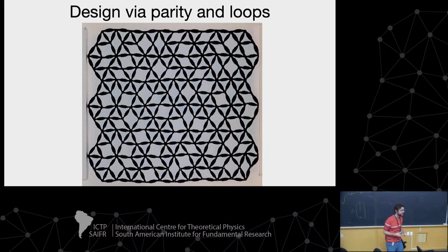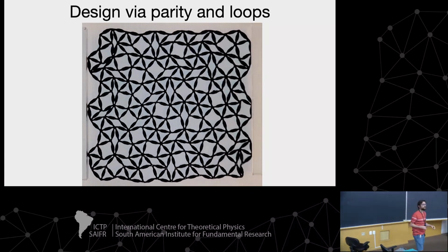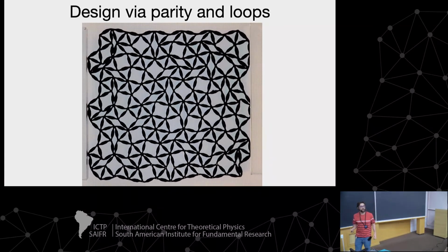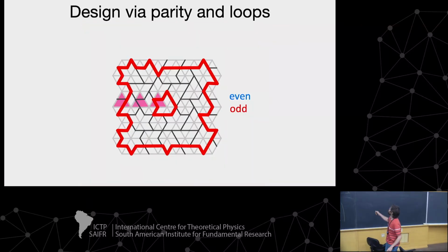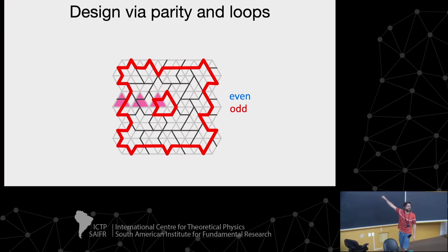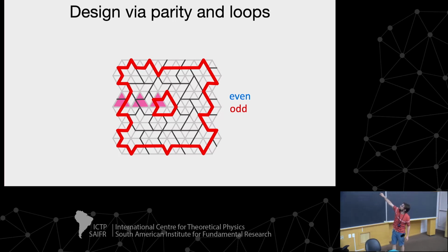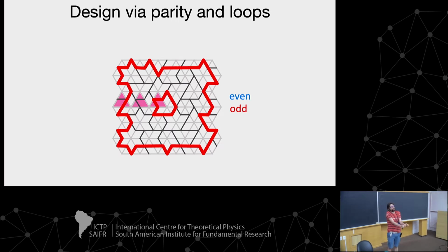Sorry. So then you say frustration would cause topological defects. Is that what you mean? Well, if you look at this and you have an odd number of ligaments, you know that the deformation is going to be opposite on either side of the strip. So now if you close the strip and make a loop, if the left side of the loop wants to close and the right side wants to open, then the loop is not going to want to fold and it's going to be geometrically frustrated.